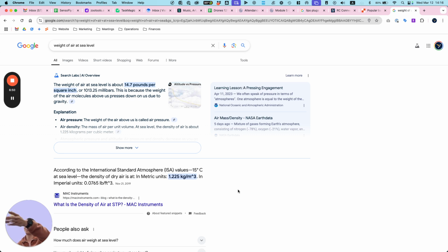So that helps mitigate that if you're trying to fly in a cold environment. So the limitation comes not from the air density, but rather from the battery chemistry. If you had a gas-powered drone, then it wouldn't be an issue. It would benefit from the colder temperature.